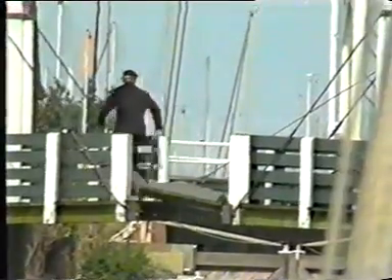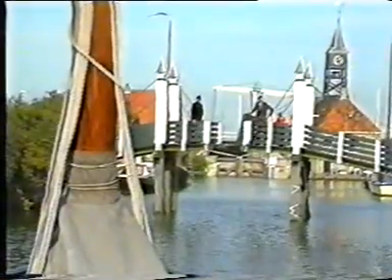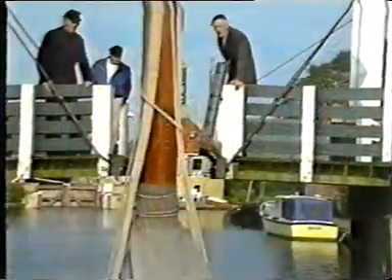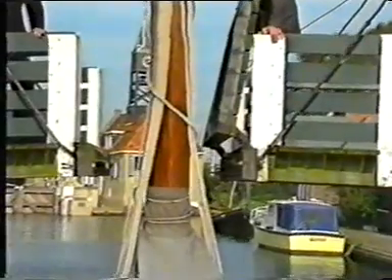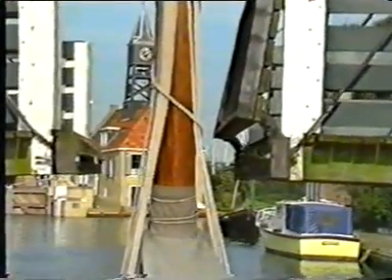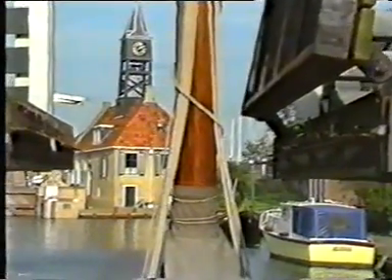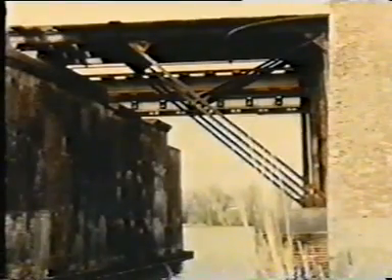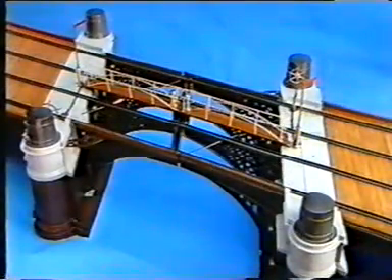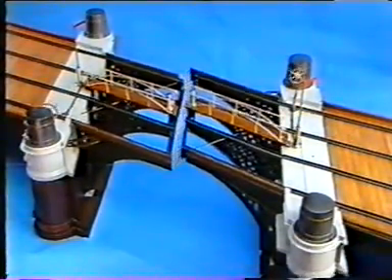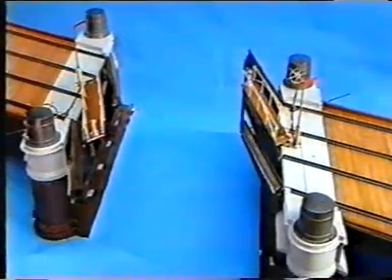In this cantilever drawbridge, not only the width of the vessel is important, but also the mast. An old type of movable bridge is the derrick bridge, applied in fortifications and railway bridges. The main girders rotate with respect to vertical axes, placed in a recess in the abutment. This arrangement makes the opened bridge look like it's folded up.